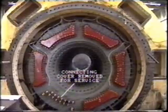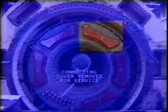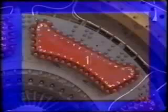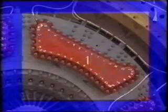Once the stator bars are fitted into the core slots, they are joined at the ends to form continuous coils or windings. These end connections are referred to as end turns. The conductors are securely held in the slots by wedges of insulating material.